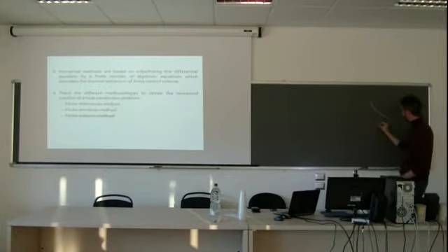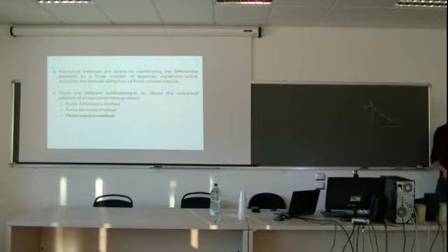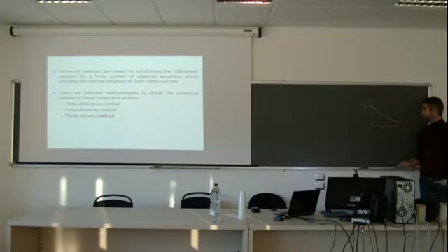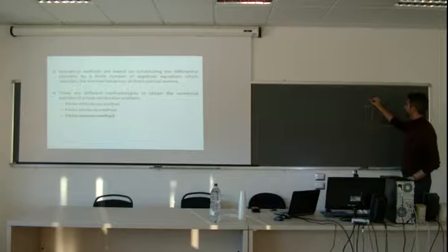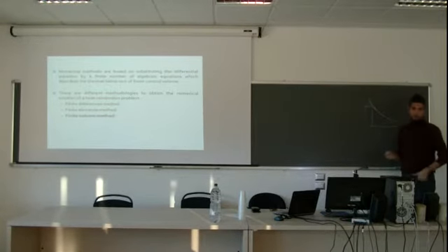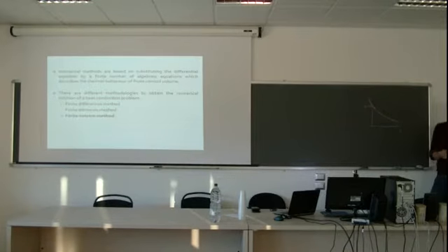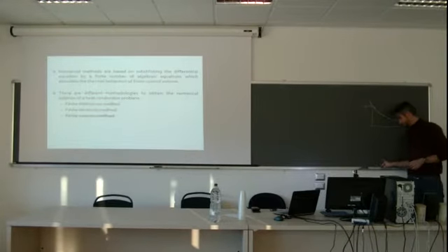If I ask, okay, x equal to this, I will have two different results: the numerical and the analytical, if I could have it. But we need to live with that. If you need more accuracy, one thing you can do is put in more nodes, more mesh, right? Then the deviations will be reduced.